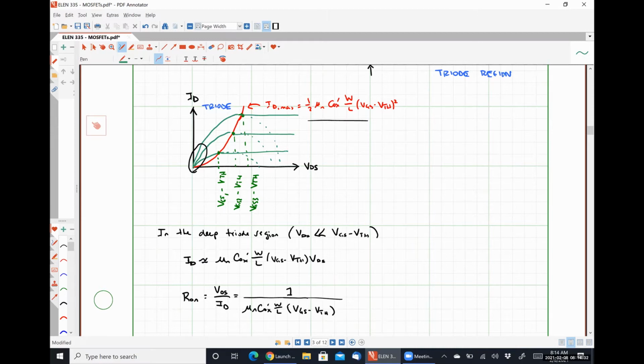The reason the saturation region was the earlier region is that for a BJT, saturation is due to an increase in bias current not causing an increase in collector current. Here, we're basing things off of voltage. Before, we effectively had a current-controlled current source model. Now we're using a voltage-controlled current source model, and it causes this little disconnect.